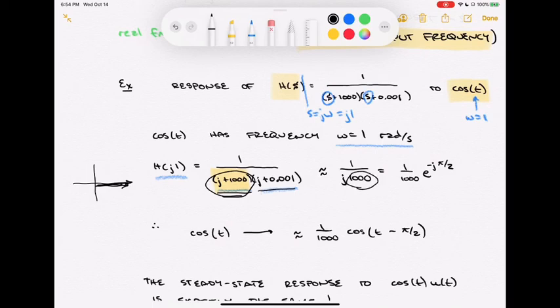In the same sort of way, if I look at this other one, j plus 1,000th, right? Now, if I looked at that in the complex plane, I'd go up all the way to j, and then I would only move over 1/1000th of a distance. That essentially still points straight up, at the same location as j. So this thing is approximately j. It's not perfect, but it's really dang close. If you don't believe it, just put into your calculator the quantity 1 over j plus 1,000 times j plus 1,000th, and you'll see that it comes out really, really close to this 1 over j1,000.